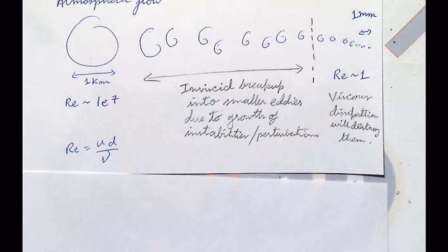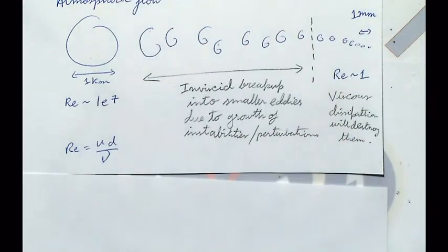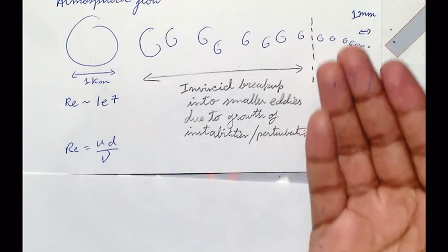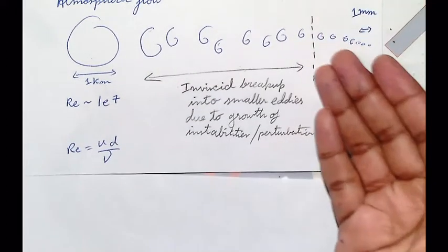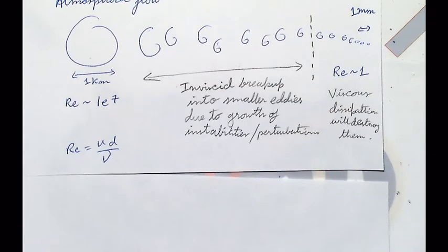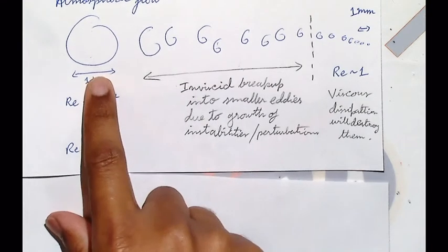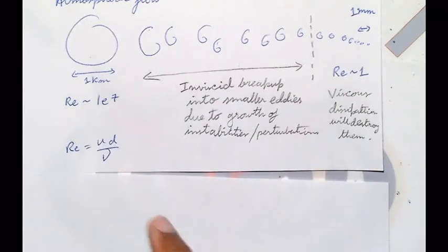And that's exactly what happens at very high Reynolds numbers. If you use a good scheme, it will blow up. If you use a crappy scheme, there's numerical viscosity, which basically kills your kinetic energy. Okay? So that's exactly what turbulence models try to do. They try to say, okay, I will let you resolve only up to a certain length scale, and everything that is not present in your simulation, I will give you a term which will recreate its influence on the larger scales. Okay? So that's what turbulence modeling is. We'll talk more about it in detail, but is this clear how Reynolds number and simulations are related?